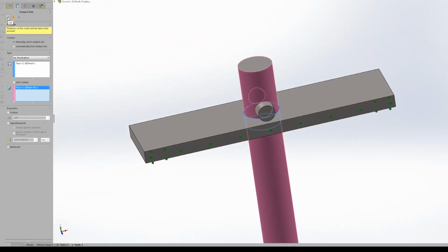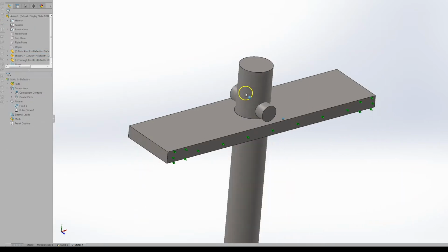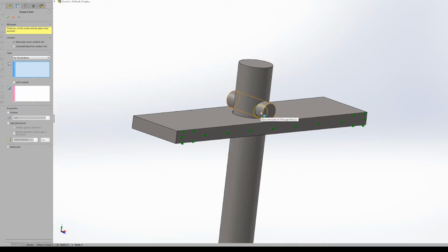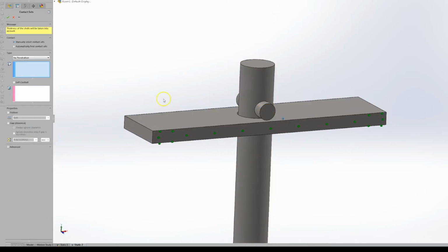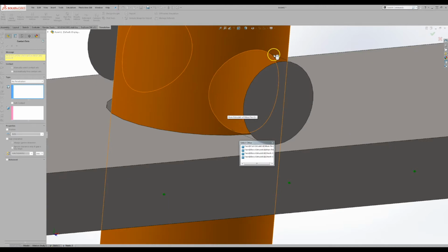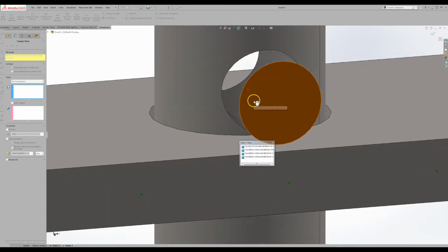That was explained to me by our CAD reseller. It's all about the efficiency of how the nodes to the elements connect. So it's basically more computationally efficient if you have the smallest face area in the blue section, the larger one in the pink section. So the final stage is to define the contact set between the cotter pin and the main body.